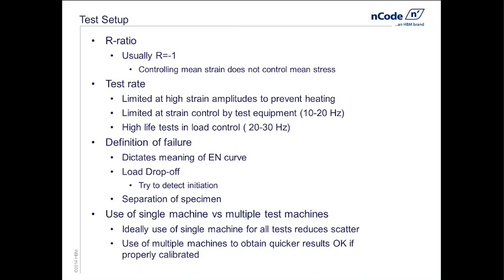With strain-life, we're putting fairly large loads into the specimens, especially at the low life regimes. And so we want to pick test speeds for our test rig that will minimize any sort of part heating. With metallic specimens, we only have to worry about that for the fairly low life regime, but we want to basically control our speeds so we keep a constant temperature on the specimen as we test it.